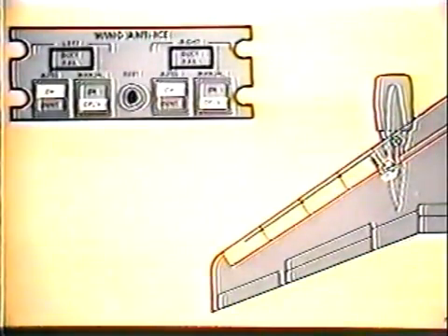There are 2 modes of wing anti-ice operation, auto and manual. With the auto switch latched, on is illuminated, and the wing anti-ice valve is energized to open with bleed air pressure. When the valve does open, the open light will illuminate in the bottom half of the manual switch. The hot air then flows through the inside of the leading edge slats and is vented overboard. The anti-ice valve will modulate to control the temperature to a specified value.